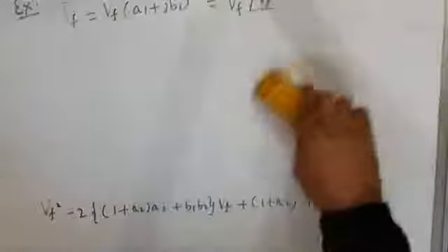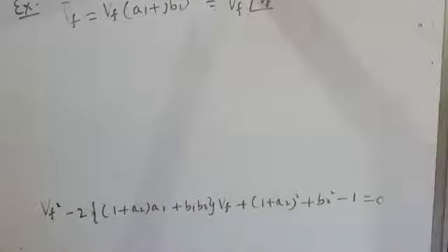But when you use the DVR for voltage compensation purposes, you have to design the DVR in such a way that it injects the voltage in quadrature with the current, so that it has to supply only reactive power and not real power. So only at the DC bus of the DVR, which is basically a voltage source inverter, you connect an energy storage like a capacitor, not an energy source, not a battery, not a superconductor, not any other source of energy.